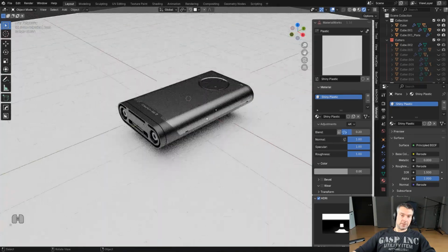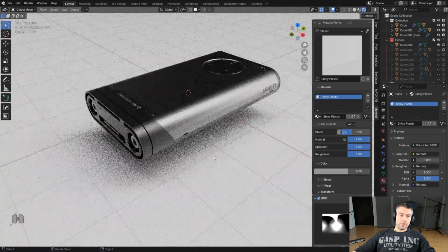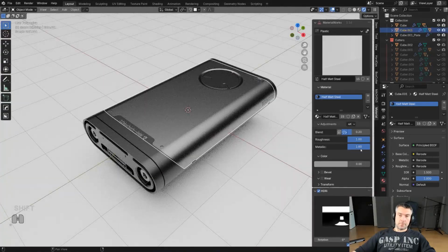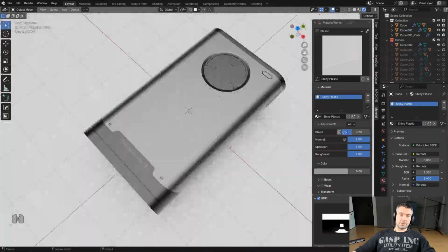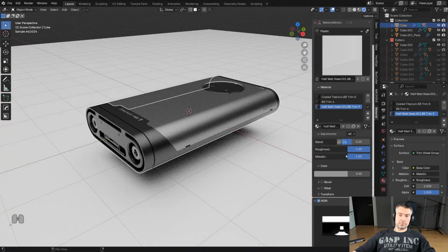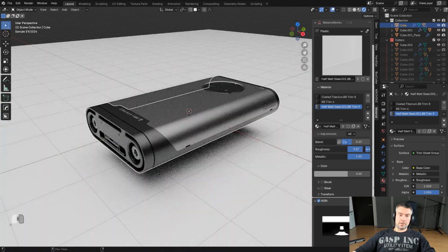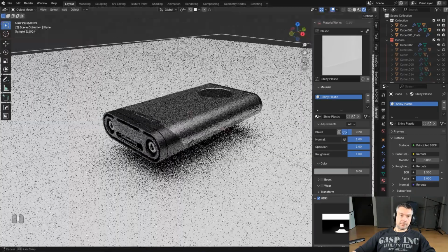Also, the reflections here, we're obviously going to be changing the HDRI to something different. But what you can do if you have kind of nasty reflections, you can always mattify your object. So you can just increase the roughness of your object to mitigate these reflections. You see, it's kind of like a mattified aluminum now, so it looks pretty cool. Same with this one. You could mattify it a little bit, so just invert this here, and you can just make it rougher, okay, if you want to. So it's not gonna be so reflective. I think it's gonna be easier to capture this.